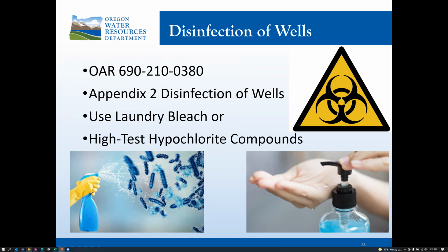Prior to or after being placed in the well, pumping equipment, sand, gravel, and well casing shall be thoroughly hosed or sluiced with water and shall be disinfected with a solution containing at least 50 parts per million chlorine. All water introduced into the well during construction shall be clean and potable. Upon completion, the well and its equipment, including the interior of the well casing, shall be thoroughly swabbed and cleaned to remove all oil, grease, and foreign substances.